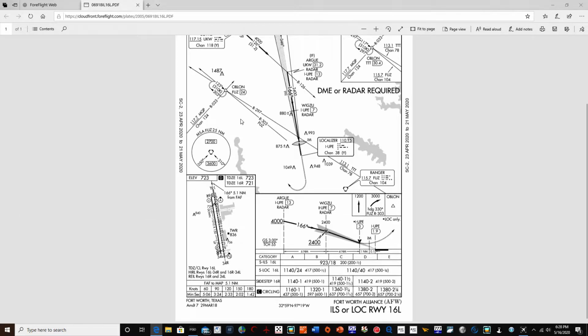Over here we see the little airport that has our approach lighting and some more airport information as well as some obstacle notes around the airport. And then you see this information here. From the final approach fix to your missed approach point, it is 5.1 nautical miles. If for some reason you lost your DME or you can't find distance, upon crossing the final approach fix you will start a timer, and if you maintain 90 knots ground speed, you will